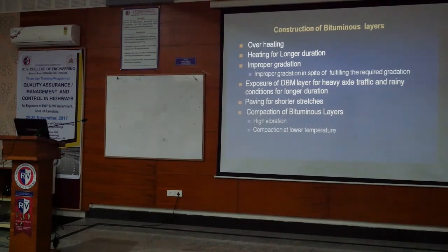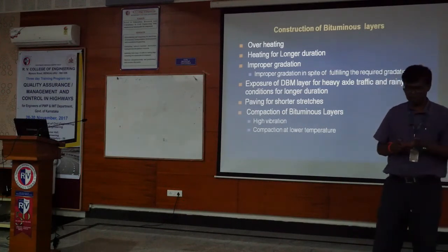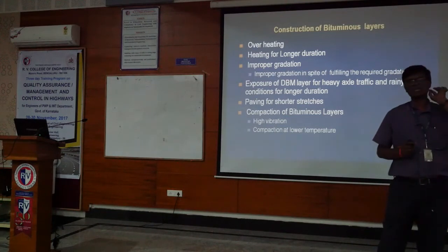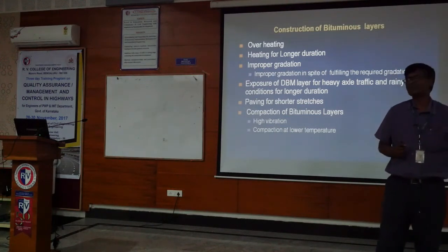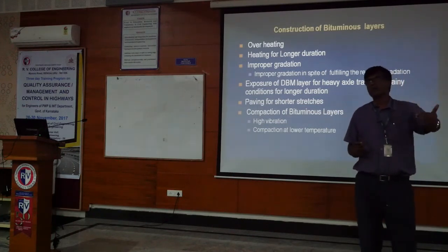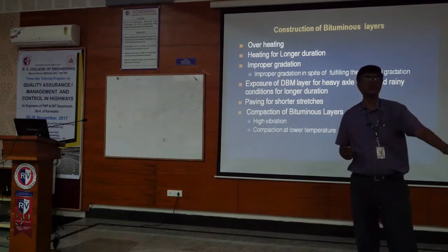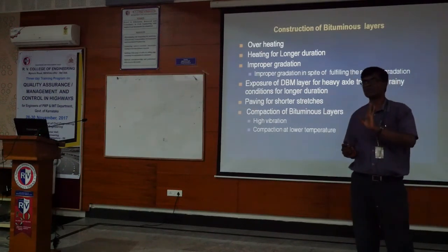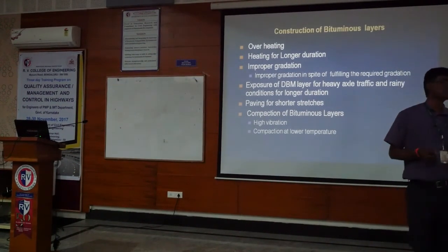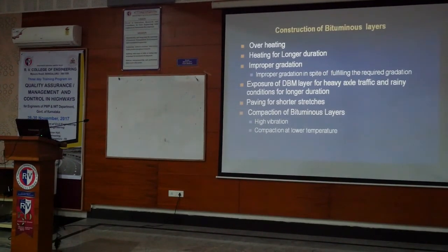In fact, the pavers coming out now will themselves give 70-80% compaction, and hardly we need another 10-15% from the roller. Maybe hardly any roller pass, 1 or 2 is sufficient. Our entire compaction is done by the paver, which also has a vibrator. If that is done properly, the majority of the compaction is done by the paver.